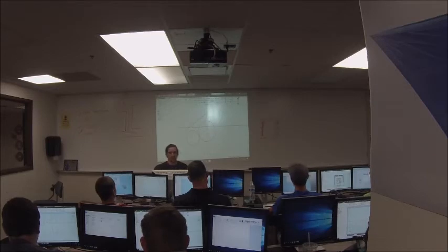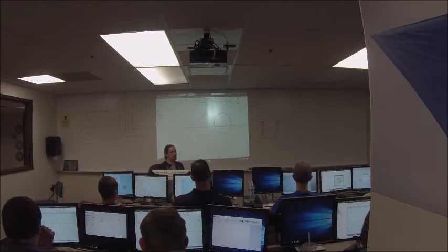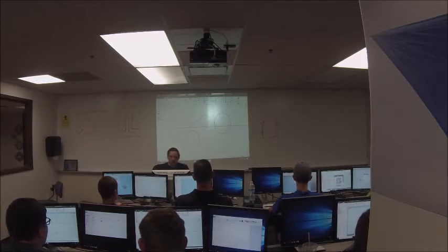This is very useful. You're going to use tangent constraint a lot because we typically don't do a lot of sharp corners because A, they're sharp, and B, especially if they're interior sharp corners, they can cause what's called stress risers, which basically focuses the strength, and your metal is more likely to crack or tear at a sharp corner. So we try to round a lot of our parts off because it makes them look nicer and it makes them stronger.